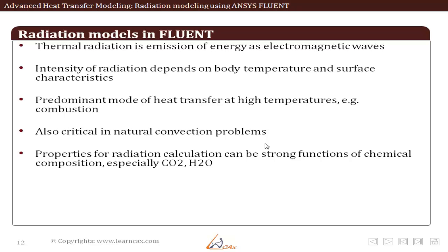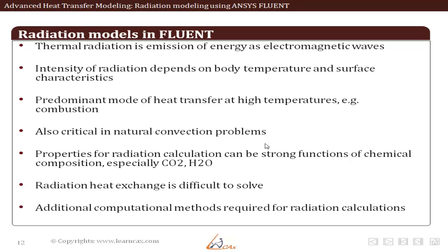So where do we observe high temperature, and hence where must a radiation model be used? There are cases like combustion modeling, automotive under hood, heating, ventilation, air conditioning, water treatment, and glass applications where radiation becomes a compulsory phenomenon to be included. Radiation heat exchange is difficult to solve computationally. We have to have additional computational models other than the momentum equation and energy equation in order to capture the radiation phenomenon.